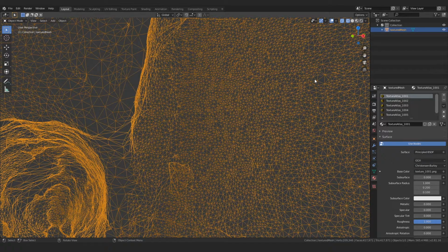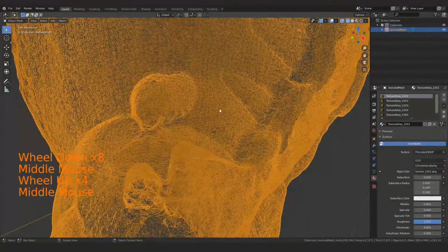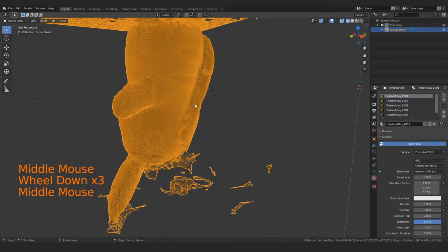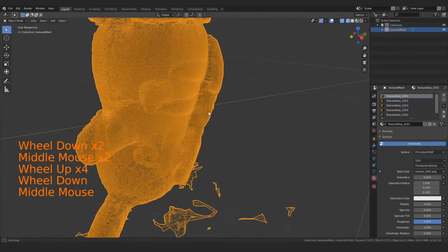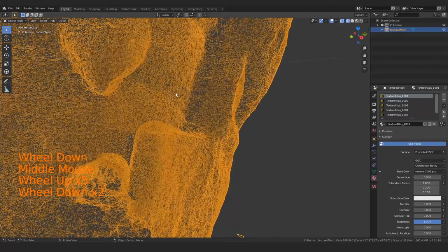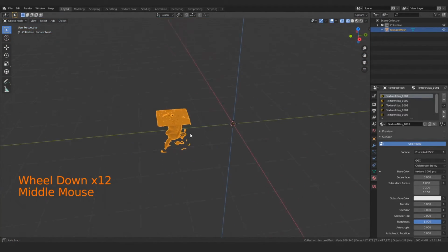So faces and triangles are essentially the same thing, although if these weren't all triangles, that count may be a little bit different, because if you have a quad instead of a tri, that's going to be a 4-sided face, and so we're going to have twice as many triangles as we have quads, because every quad is 2 triangles. That's simply how 3D works. Just if you're not familiar with it, maybe dig into it a little bit deeper. There are a number of 3D courses and things like that out there. I don't want to waste too much time trying to get into the minutia of it, but essentially that's what we're looking at. We're looking at points that are plotted out on a grid that has 3 axes.